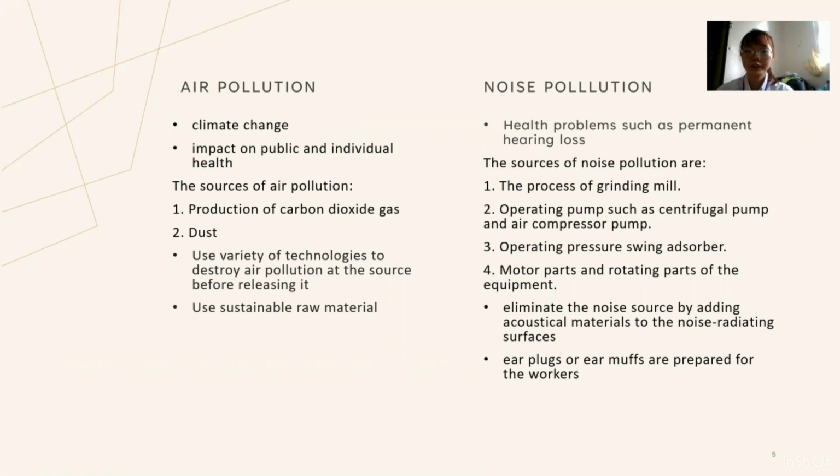Next is our noise pollution, which will cause health problems such as permanent hearing loss for the workers. The sources of the noise pollution are the grinding mill, the operating pumps such as the centrifugal pump and air compressor pump, the operating hydrogen adsorber, and the motor parts and rotating parts of the equipment. We can eliminate the noise by adding acoustical material to the noise radiating surface, and earplugs or ear muffs are kept for the workers when working.